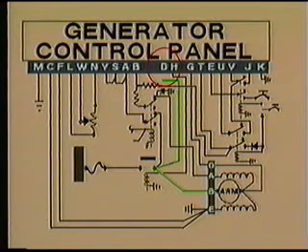Since the control panel didn't see anything there, it just kept turning up the output until the over-voltage circuit took over. The control panel was performing exactly as it should have, but because it did not have all the needed information, the result was a malfunctioning circuit. Keep those important sensing points in mind while troubleshooting the generator system.